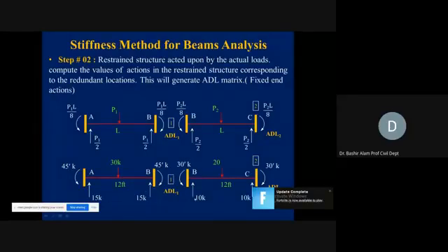We are not taking the 15 here. These also correspond to this one location, but remember that rotation was our unknown. It was not the deflection, settlement, or vertical translation. If vertical translation was unknown here initially, then we would include this 15 and 10, which are the vertical reactions. Those would be the corresponding actions then. But in this case, plus 45 minus 30 is our ADL1 value.